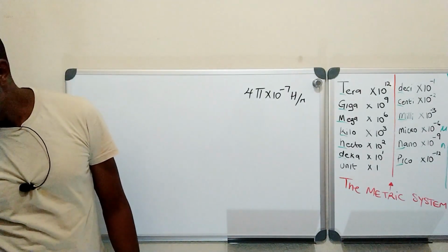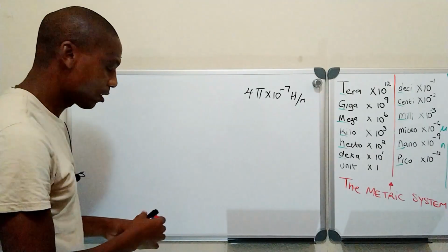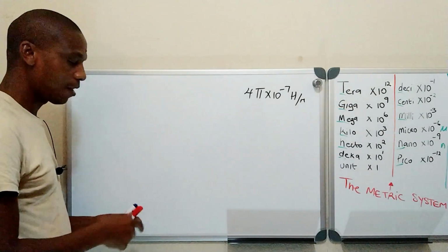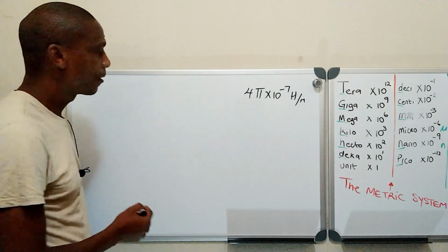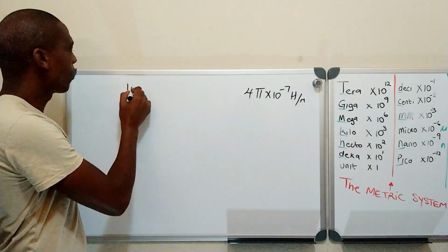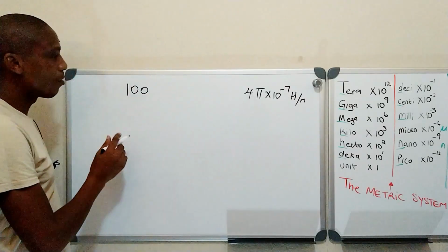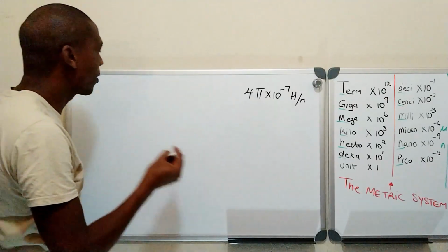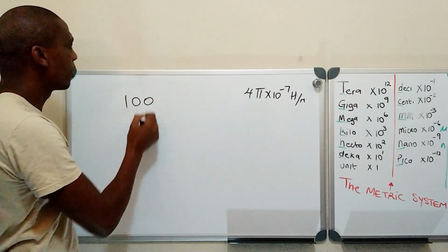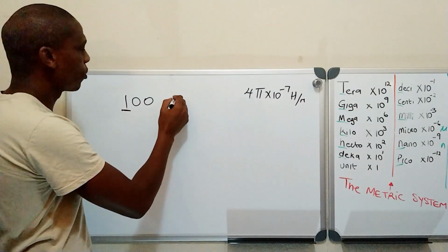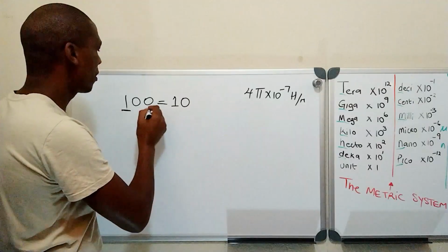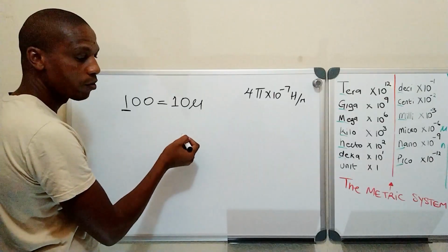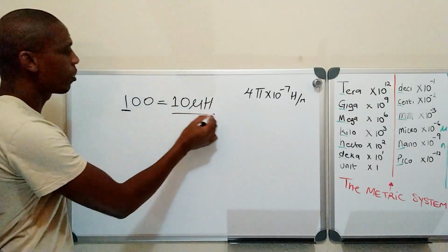Now the SMD inductor, they come with numbers. The right numbers there depicted. You see a number? Can you see a number there at the back? What is the number there? 100. I want to start afresh and show you what represents what you should know by now. We did it in a resistor, we did it in a capacitor. You should know by now in an inductor. You know, this is a digit, so it's a 1. There's another digit, there's a 0, so there's nothing. Micro who? Micro Henry. So that one is 10 microhenry.